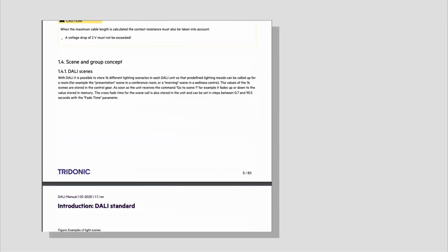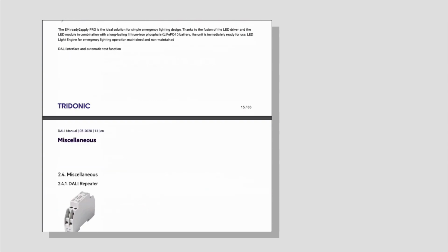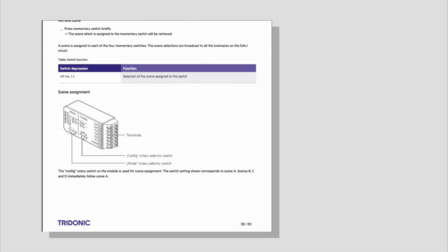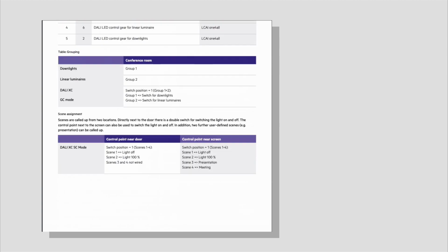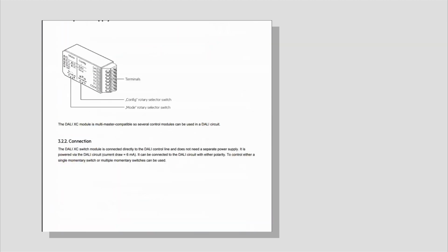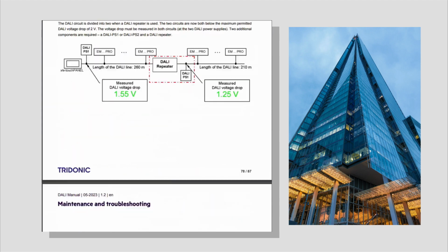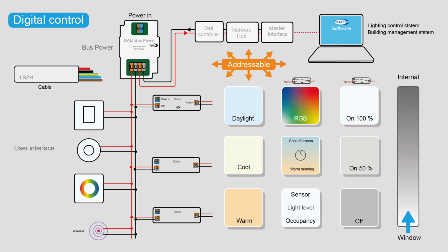And it's kind of simple and it's kind of complicated. This is one manual from Tridonic, which I pulled off the web, and this manual's 169 pages long. It is basically quite simple, but because this can be managing a massive building, it can become quite complex as well. Pretty much like that 1 to 10 volt lighting, except this is addressable and you've got a lot more control. We're not using mains voltage for dimming. Mains voltage is taking the drivers and such, but the control is on a bus. It's 16 volt control communication, so the wiring is quite simple.